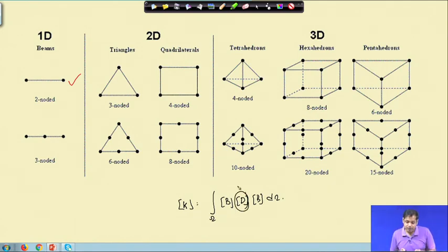And then B depends on what degrees of freedom you have at every node, how these degrees of freedom are interpolated, or how those degrees of freedom are represented through a functional form, through a function that gives you B. So, B is essentially the strain displacement relation, not necessarily, but in the examples that we have been discussing in that context, B is the strain displacement relation, right?